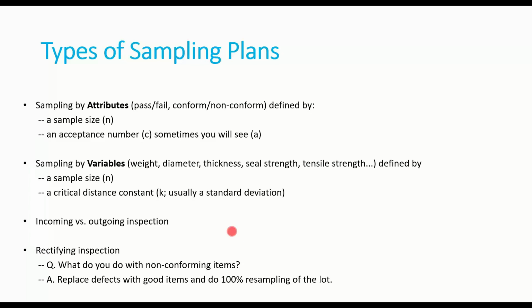Okay, but it's particularly wasteful of information and materials and work and time when people go to the trouble of taking measurements on variables data and then compare each data point to a specification limit and treat them as good or bad, or in or out, right? Or go, no go. So don't change your variables data into attributes data. Next month we'll show you how to do the variables.